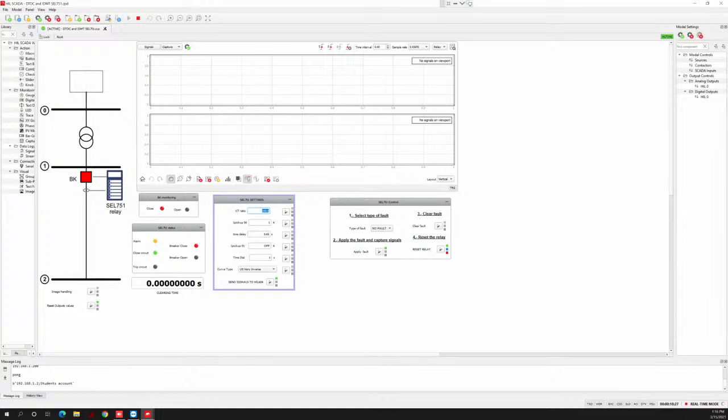Here you can see all the functionalities that this relay has. For instance, you can see that we have frequency settings, vector shift, power factor, overvoltage settings, inverse time, all the settings, but I don't find directional, neutral overcurrent. Yes, line, it is the maximum phase overcurrent. This one, yes. Here you can get the setting for the protection 50, that is the ANSI number.